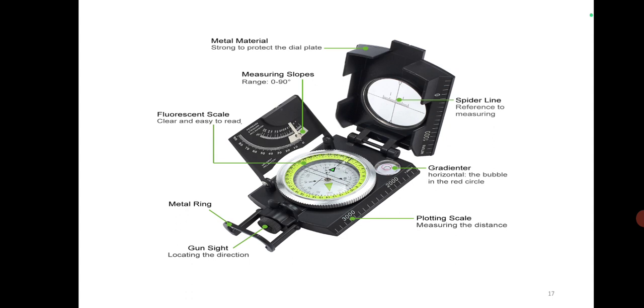And this clinometer compass, it is fixed to a rectangular plate. The plate may be made of cast iron or plastic, and the 180 degree line, that is the north-south line, is made parallel to the length of the rectangle, longer side of the rectangular plate, and is marked 0 to 360 degree, marked in the anti-clockwise direction in clinometer compass.